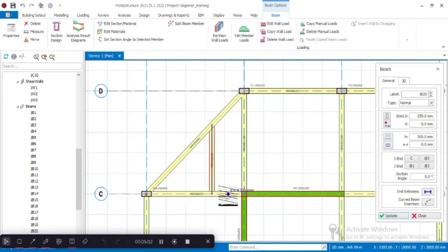So it's showing me the distance of increments. I can place from the end of the distance, let me say 250 now, showing me the points as it goes. When I reach a point I'm interested in, let me say this, I wanted it at 2200. Click on this point and it creates.